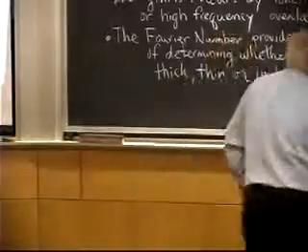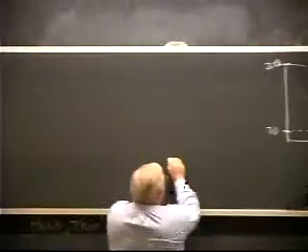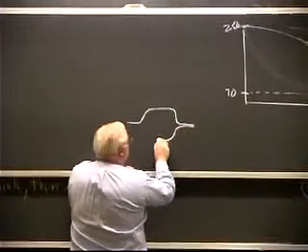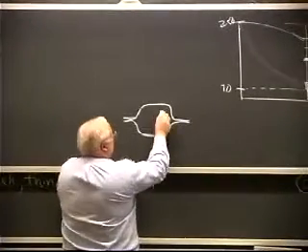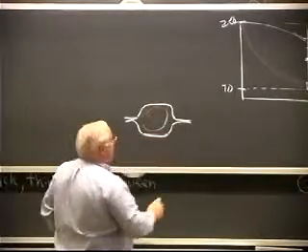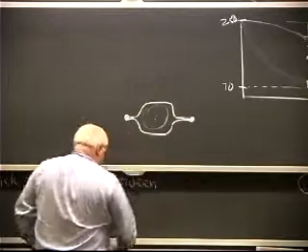And they actually have what we call an omega seal weld. So I've got a clamshell like this, and another clamshell like this. I'm exaggerating the flanges here. And your catalyst is in here, and this is basically the stainless steel can. And you've got to make a seal weld that is gas tight right there on the end.